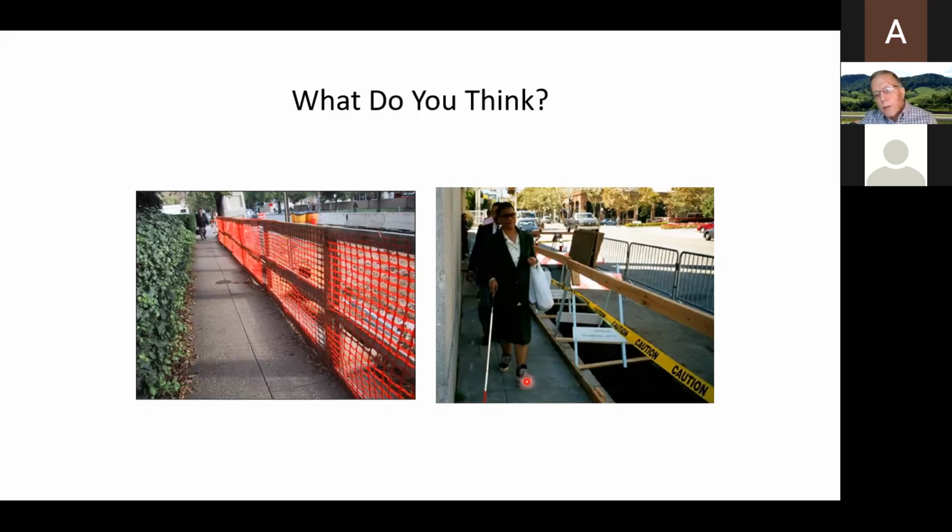And how about the one here on the right? This looks like it's 5 or maybe even more feet wide, but I don't think this kick plate or toe board here is 6 inches high. I don't know what you all feel, but to me, that's not high enough. And this is a good example too. Let's say there was an 8-inch high board here. That would comply with PROWAG, but does that comply with good construction safety practices?